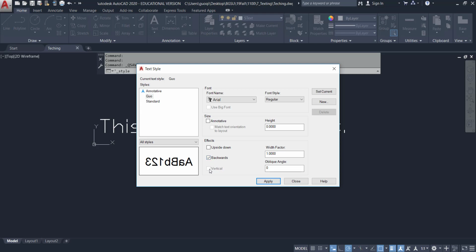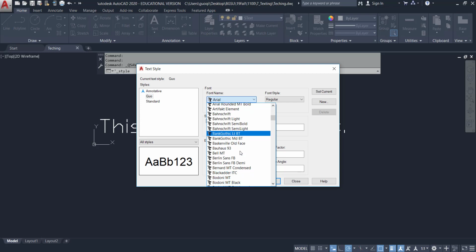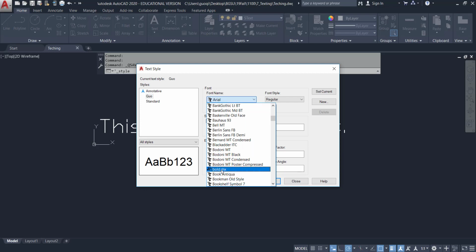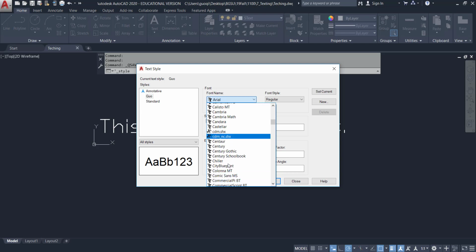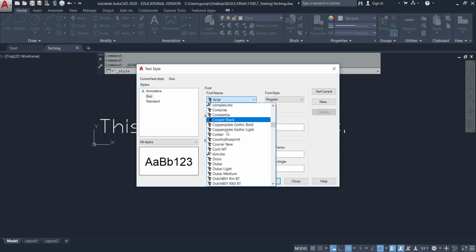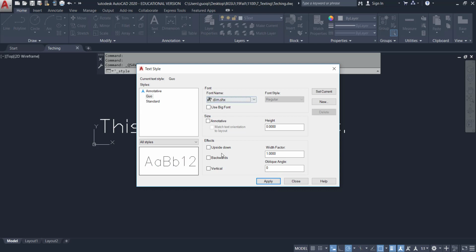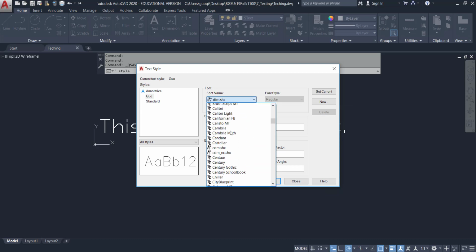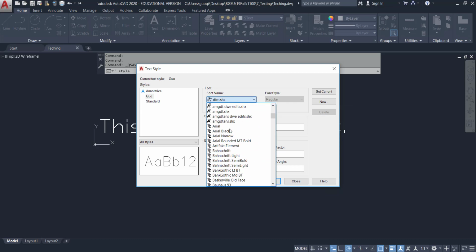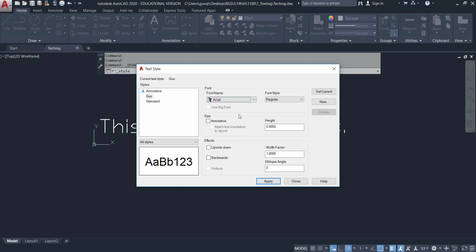And also some of them will be available for vertical. So you probably check on any text font with SHX at the end. Some of them will work and some of them still don't. So such as the dimension one will work. So if you selected the font as the dimension, then you could make that vertical. And let's go back to Arial ones. So right here.